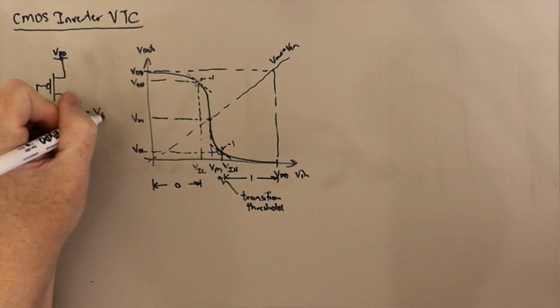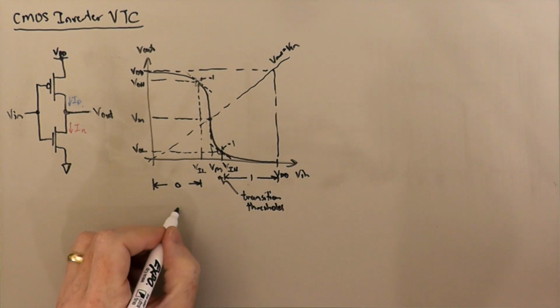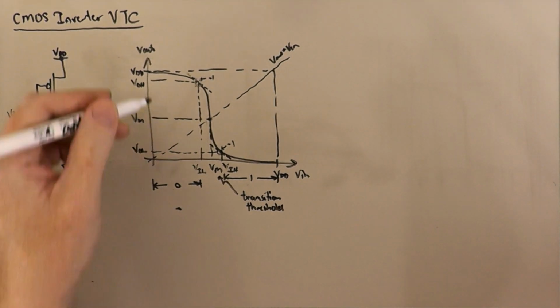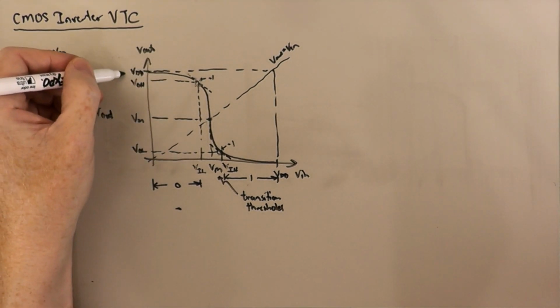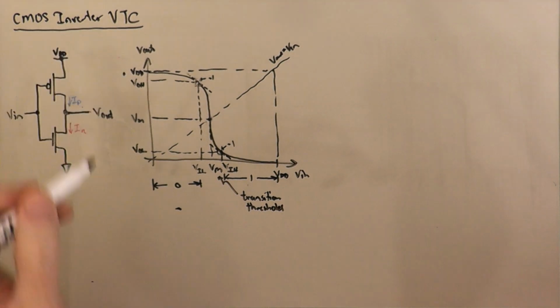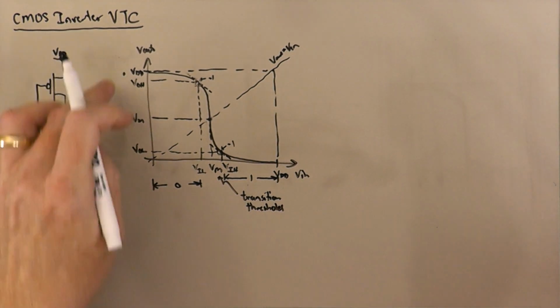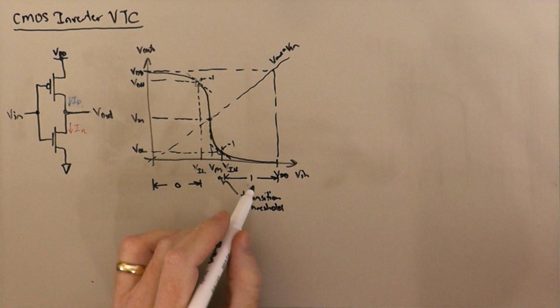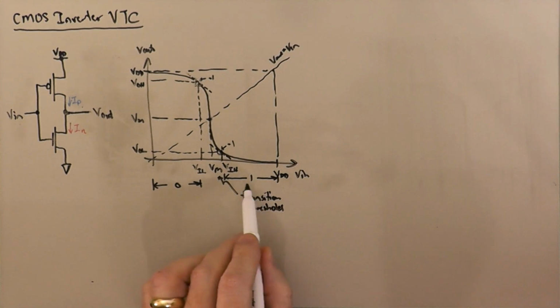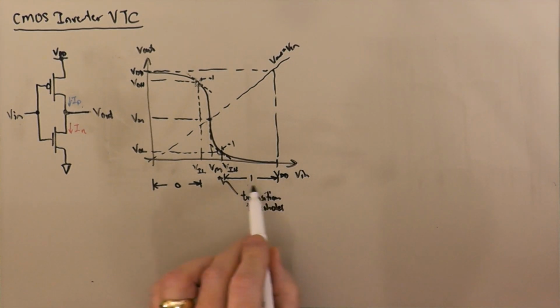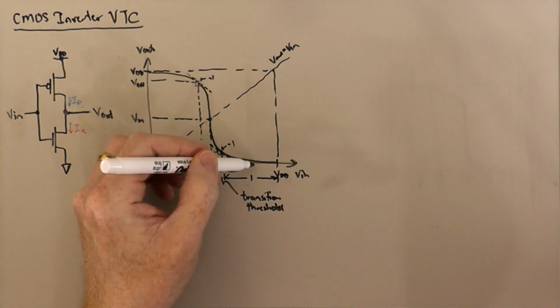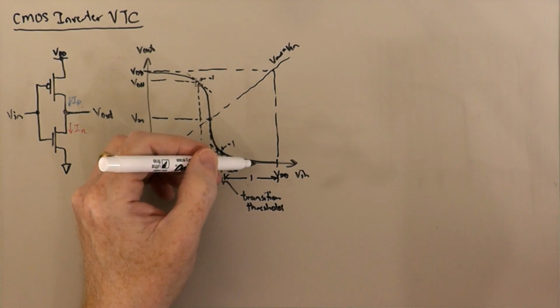So this is V in, this is V out. If I wiggle around down here by some amount, that gets mapped by this curve into wiggling around the output by a smaller amount. Same is true over here. If I wiggle around over some range here, that gets compressed into wiggling around in a smaller range on the output.